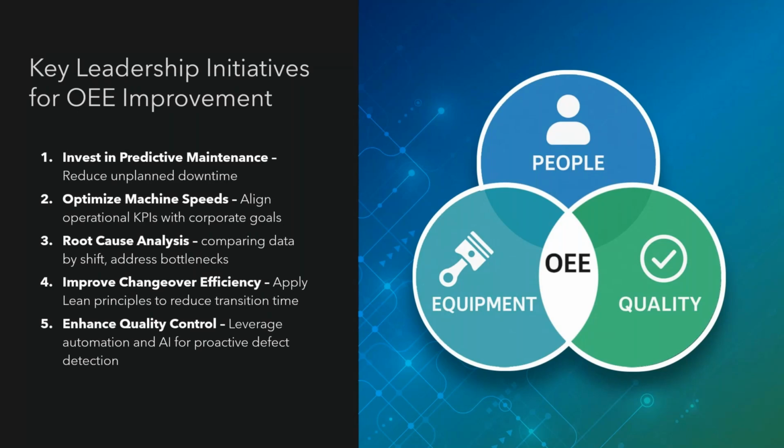So being able to look at different line speeds of different cells, and whether we're reaching cycle times and optimizing those machine speeds, or distributing workforce or automation equally across the line, is going to be very important. That's something we're seeing a lot more, especially with increased data analytics tools.